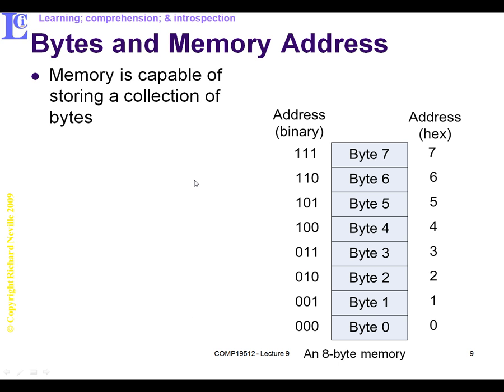Now let's move on and try and have a look at this diagrammatically. So if this was byte addressable, each one of these locations might store 8 bits. But we can see here in this diagram we're depicting as having only 3 address lines. Okay, so with all these possible options and combinations, we can have 0 to 111 numbers of 8-bit locations. So we can have 0 to 7. So there's 8 locations we can address with 3 bit address lines.